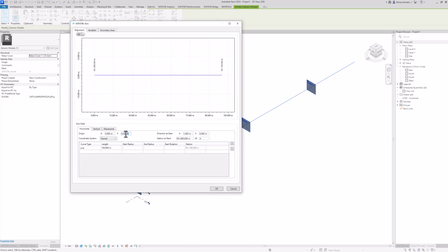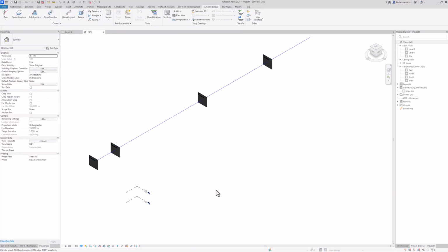And what I want to do is give it a horizontal offset of, let's say, 20 meters in Y direction. And this is now something that you don't necessarily have to follow, just if you also downloaded the LandXML file. But now what I want to show you is the axis import function.